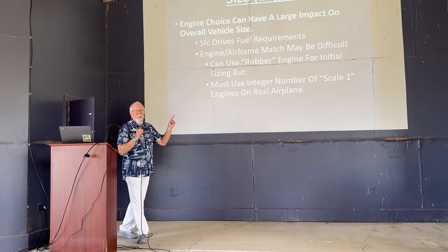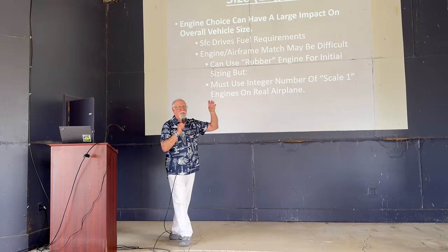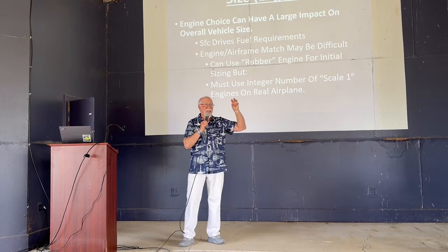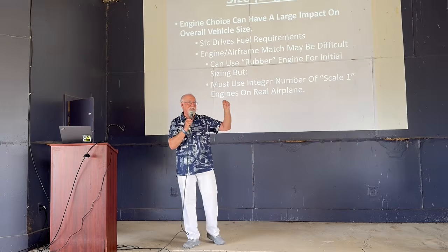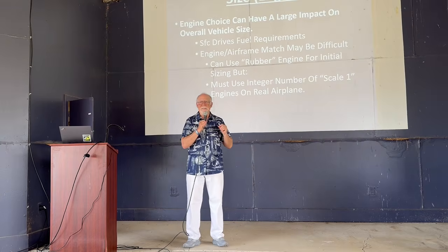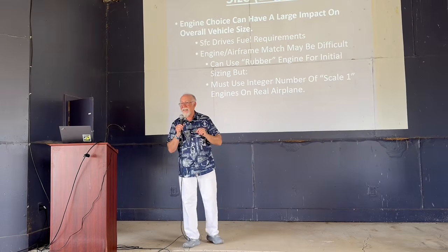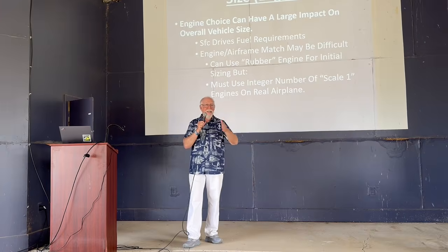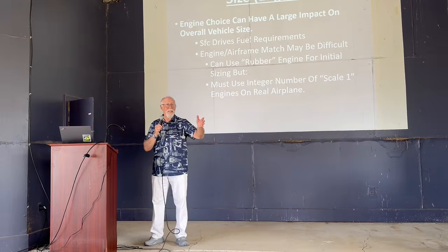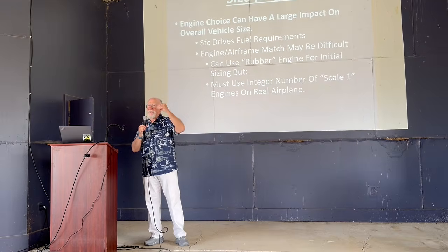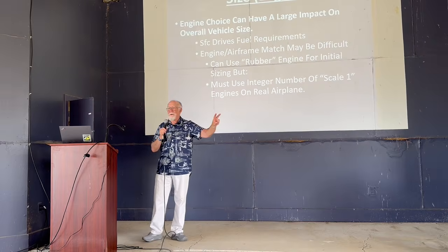Final thing, in your sizing software, you can scale engines infinitely if you've got a good cycle deck, but the engine manufacturers will not sell you a 0.9 scale engine or a 1.05 scale engine. Unless they're designing the engine for you specifically, you have to go and say, okay, I need an integer number of scale 1 engines.